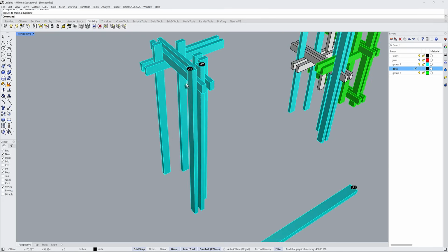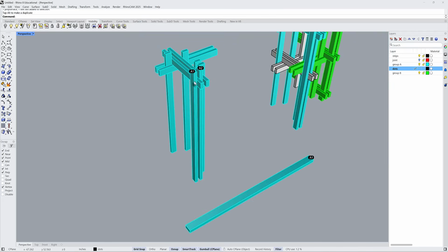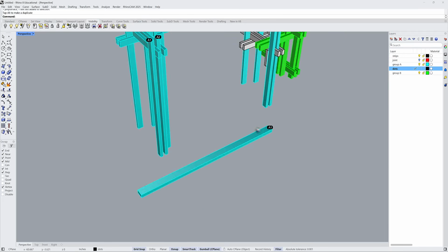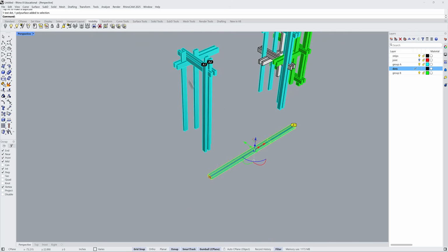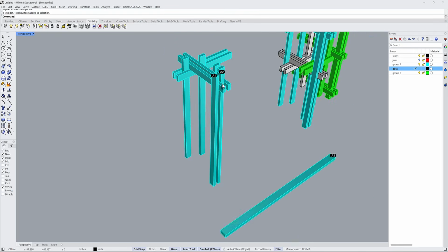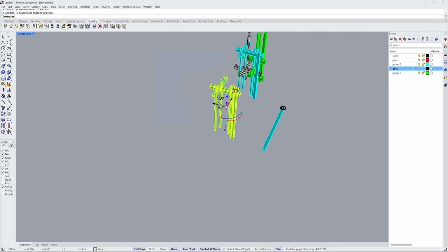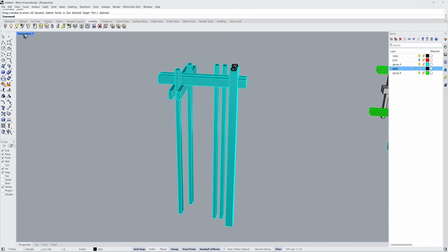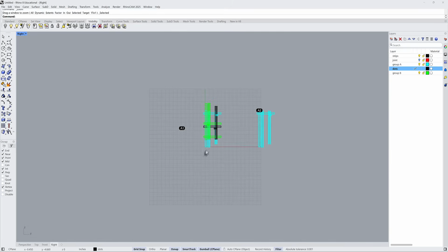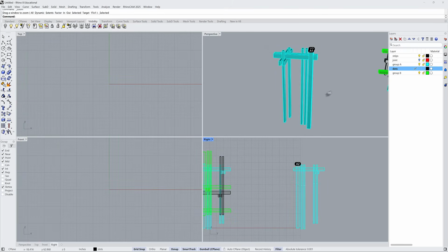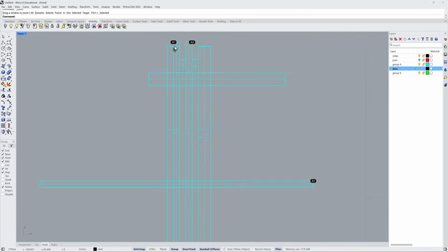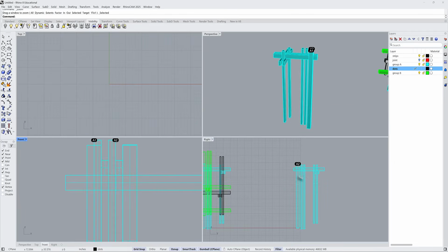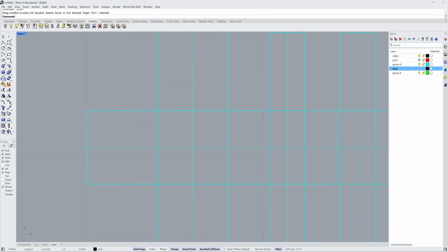We also need to get some information on where the joints are if we are drilling holes on this. Or if you want to do it on the go, you can also think about marking them so they can work like a marker. So how do we put the joinery here? Again, let's say we want to put a cylinder there. I can go to an orthographic view that looks at that elevation. The pieces are here, so I want to find A1 and A2. Let's say we want to drill a hole at this intersection here.